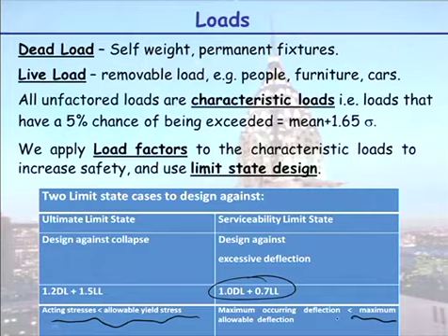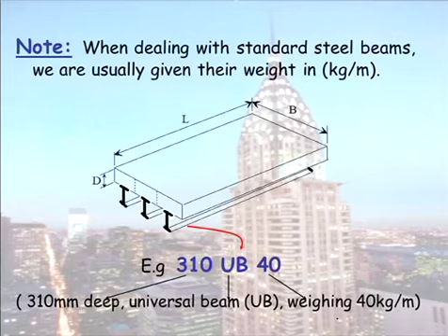And if something is within the range of both, our building is acceptable. If you say, no, the beam deflects too much, then you have to put a bigger beam in, bigger than is required for strength. Or no, it's going to fail, but it's not deflecting too much. You still have to put a bigger beam in, and it'll deflect even less. So these are two independent checks you do, and you'll be doing that with your third project.